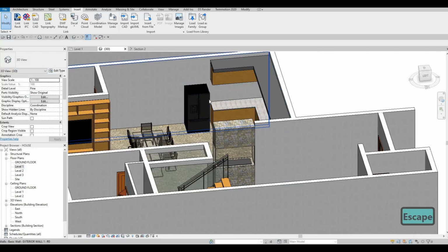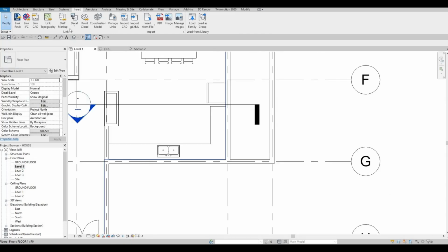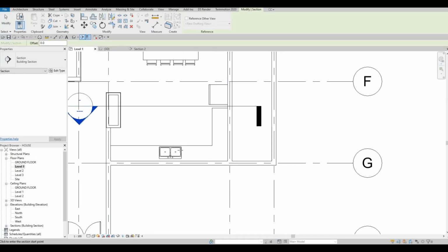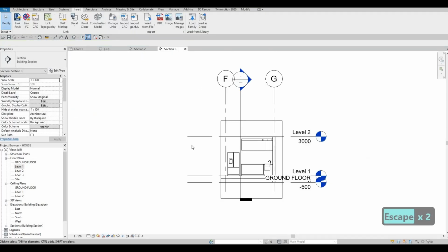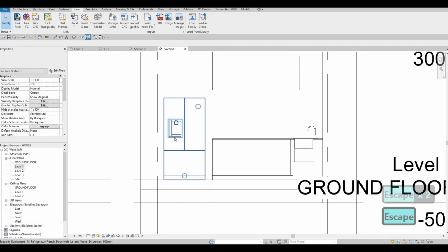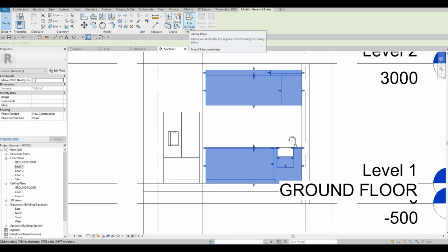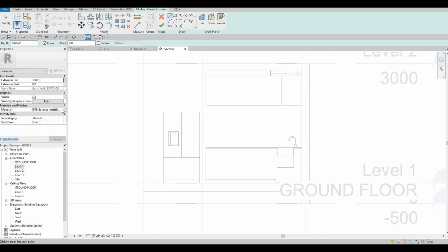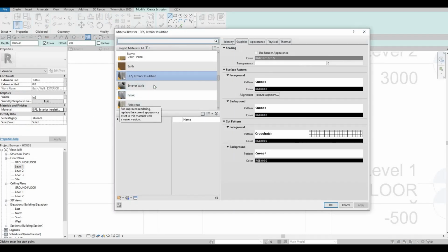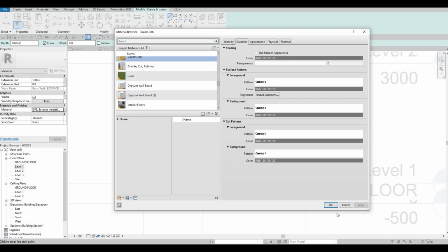And then now this one is the look. We could just create a big casing right here. So the good thing now is to add another section so that it's now facing on this side. So let's create that, and then now we could create our casing first. I'm gonna use this one, in place, edit that, extrusion, pick a plane, and then we're gonna select this wall, and we're going to select the same material that we have right there.